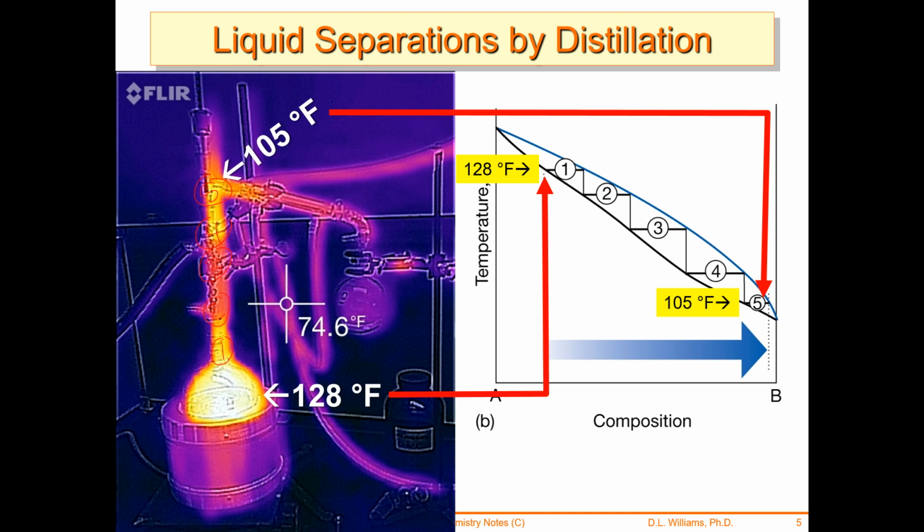It's not a fusion reactor, but still, you might have a burst of vapor that creates a current and a wind that goes right up the column. And this is to stop that wind. Okay, so you don't want a windy column or you'll get too much carryover. Yeah, so you want it to be a tortured path up that column. And that will also set up a really good temperature gradient.